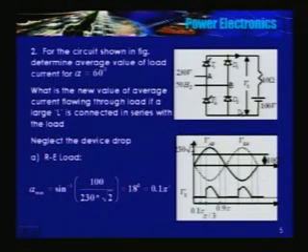Load is R and E. I did tell you that the difference Vi minus E is across R. So voltage across R is nothing but I into R. So V minus E is 0, therefore I should be 0. So at pi minus alpha min, this is the instant wherein E is equal to the input voltage Vi, and current becomes 0.